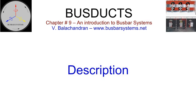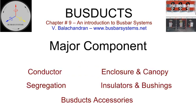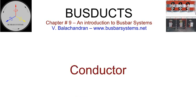Description. Bus ducts are custom-built products that are required to be manufactured in a factory and installed at the site. Few non-segregated phase bus of relatively lower current rating, busbar trunking, that are installed in assembly shops, factories, and commercial complexes, can be put together at the site with standardized factory-built assemblies with minimum customization. These are for secondary distribution. Major components of a bus duct can be broadly categorized as conductor, enclosure and canopy, insulators and bushings, segregation, bus duct accessories. Conductor. The conductor material is either copper or aluminium.